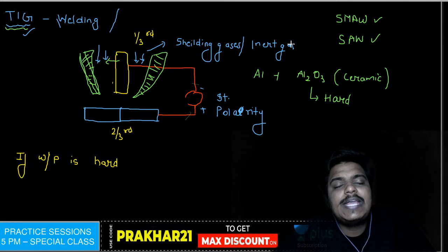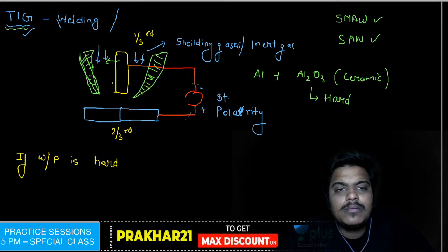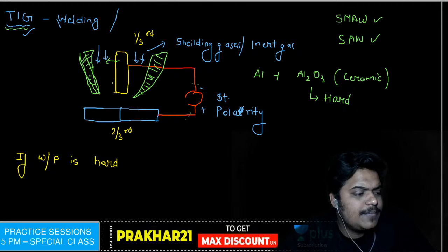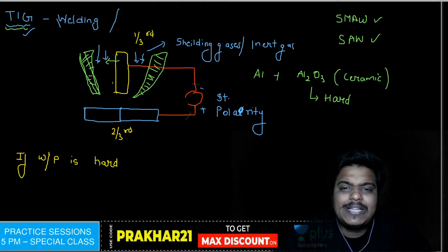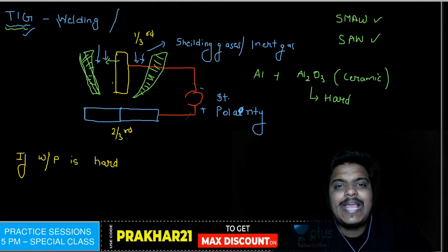In application, write this: TIG is specifically used for aluminium and its alloys. The process you know: the workpiece will be connected to the anode, the electrode will be connected to the cathode, and the electron movement will break the Al2O3 layer and the welding will take place.